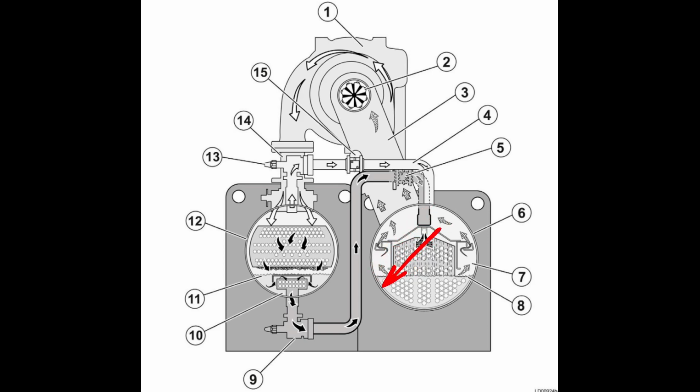But in terms of where the line is tapped into the evaporator, that's dependent upon where that liquid level is expected to be, and where that refrigerant is going to have the highest concentration of liquid refrigerant with oil in it.